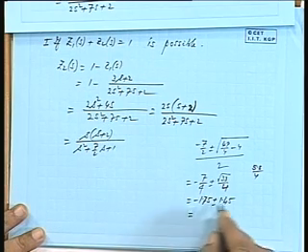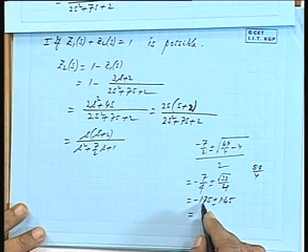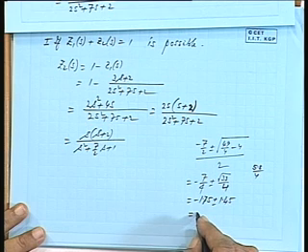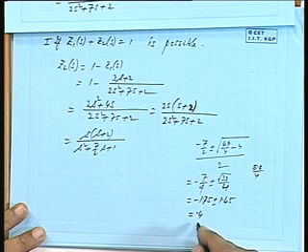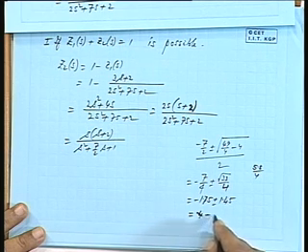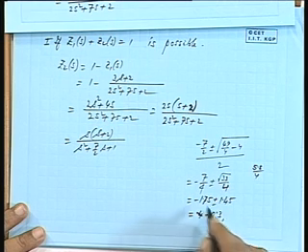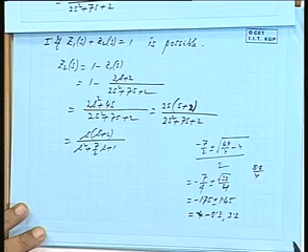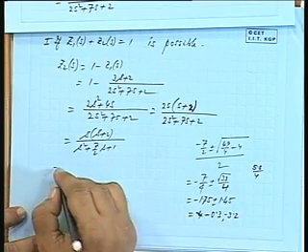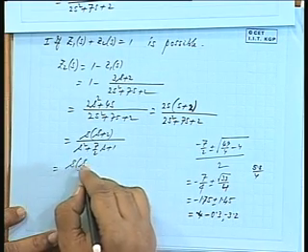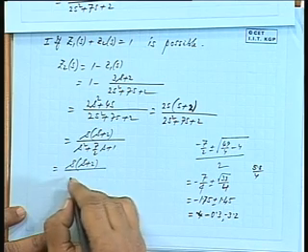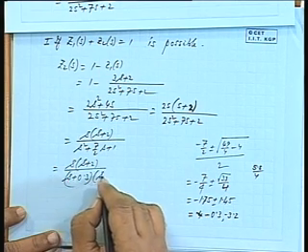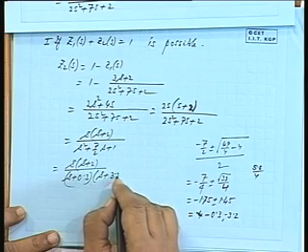Now you see the distribution of roots, minus 1.75 plus 1.45, so that will be minus 0.3. The other root is minus 3.2. So this will be approximately s into s plus 2 divided by s plus 0.3 into s plus 3.2.